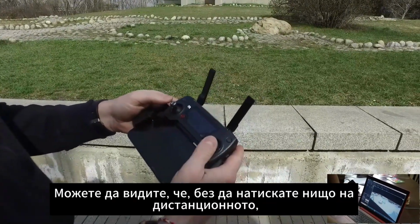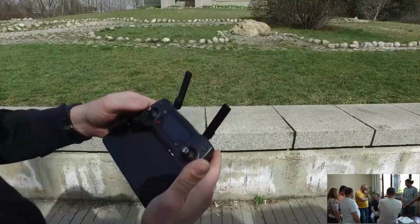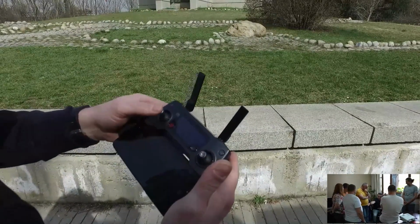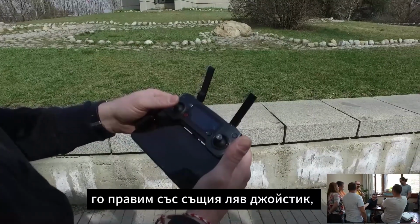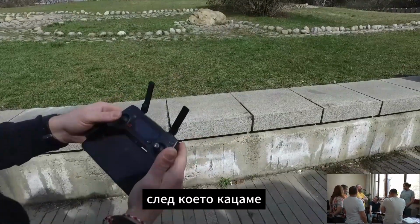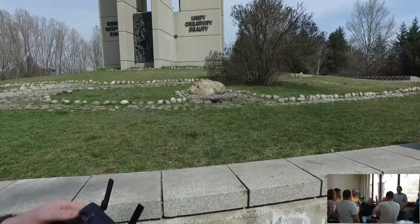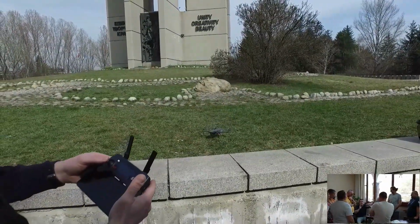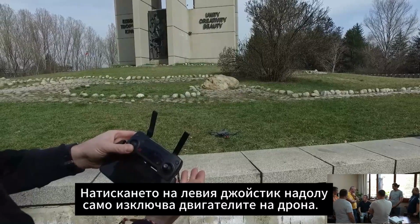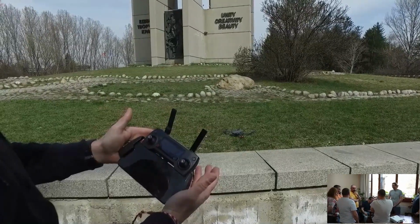You can see that without pressing anything on the remote, the drone is hovering in the air and even responds to our commands. If we want to land the drone, we do it with the same left joystick, but we push it down. We take off up, we land down. Pushing the left joystick inward only turns the drone's engines off. This is takeoff and landing.